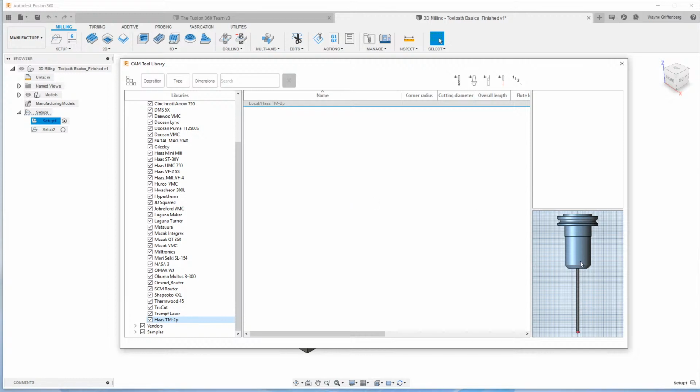I know it's still showing my probe because that's the last tool I highlighted, but let's create a new tool. So let's walk through the creation of a new tool. Up here on the upper right, we have some capability of creating a new mill tool. We can create a tool holder, and we can also import tools from our tool holder vendor library as well. We can create a new turning tool, a new cutting tool for our laser, water jet, or plasma. And then I'm going to show you what the tool numbering does in just a moment. So let's create a new mill tool.